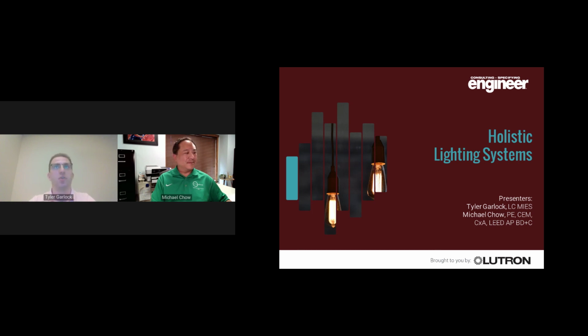So this one is a really hard question to answer because ultimately it comes down to the end user and what they're comfortable with. I recently had a project here in Madison where the whole building structure was wood timber, and it had a ton of daylight and fenestrations in the building. So we actually went with 3000K to bring in the warmth of the wood. But because there was the daylight, which is typically around 6,000 Kelvin, maybe a little bit higher, it offset that balance. So there's a lot of factors that can go into answering this question.